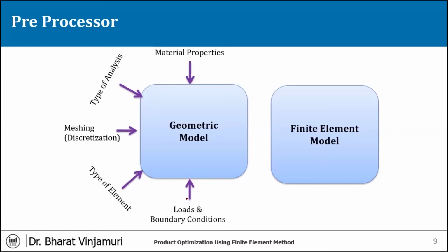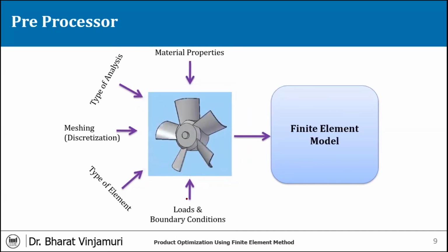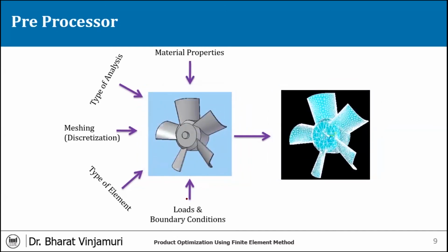Now our concept is to take the outcome of the preprocessor, which is finite element model based. So here the physical model looks something like this, and the finite element model is looking like this. The first model doesn't work. That makes no sense for us. For a real-time user, it may not make much sense. But as a finite element model, it can be analyzed. I can apply all the things because it has got all these capabilities. So once it is done, this is what we call the preprocessor.